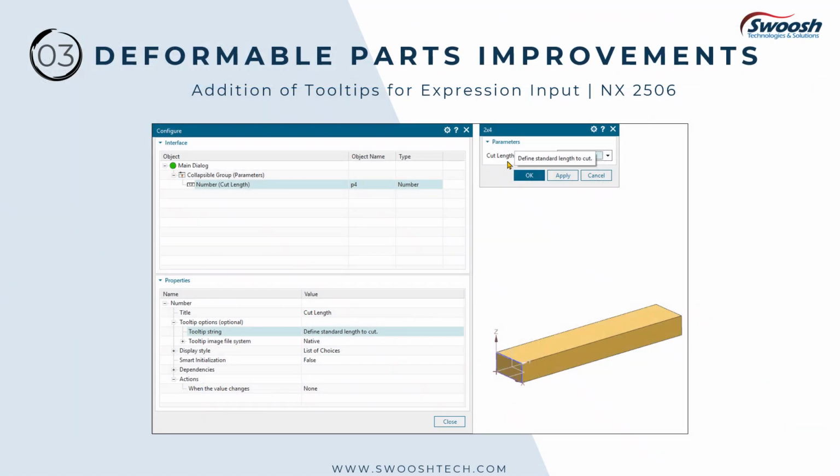At customer's request, in the June 2025 release of NX, Siemens have expanded the ability to add mouseover tooltips to expression inputs in the Template Studio Author environment, which includes deformable components. Descriptions and/or images on these tooltips can help the end users quickly and easily understand the design intent behind each input and guide them to start using templates more quickly and with greater confidence.